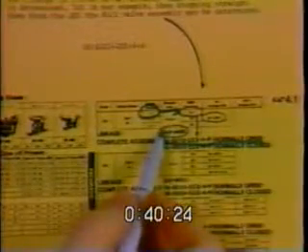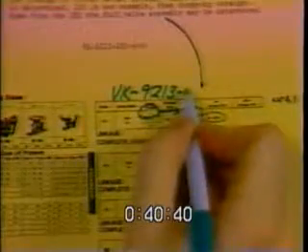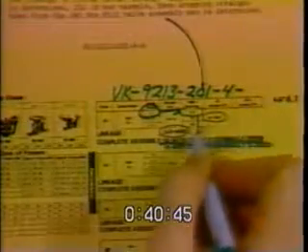Notice there's also the linkage here. But just to give you the complete valve assembly number and what it is, it's V, K, valve, and the K represents that it's a pneumatic assembly. The valve number stays the same, 9213 dash, and now I have the actuator code number, 201 dash 4 dash, and our port code in our example was 7. This complete valve assembly number will give you the valve, the actuator, and the linkage combined.